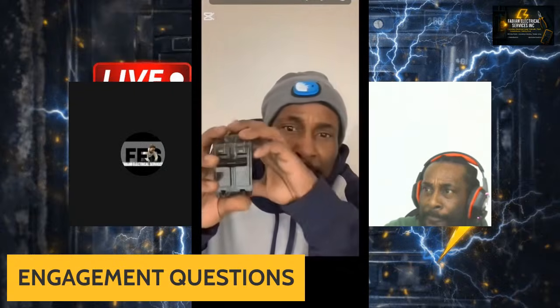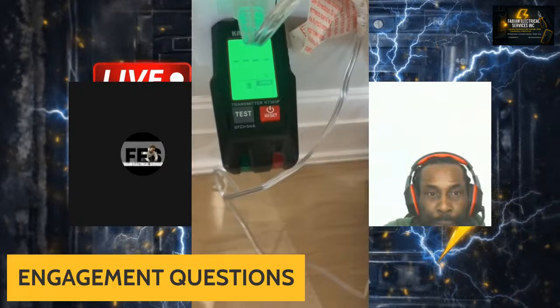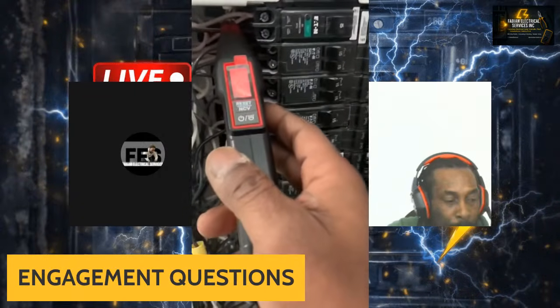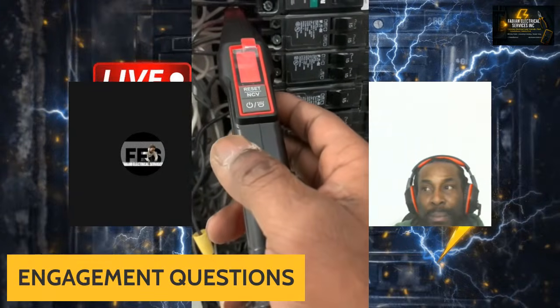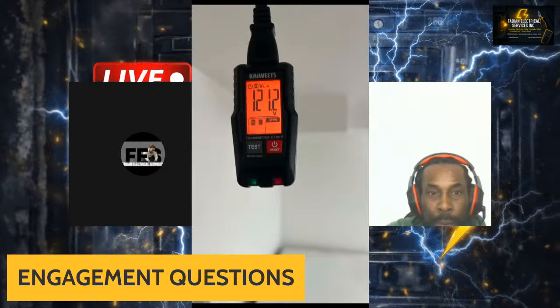Most electricians are using breakers wrong. A breaker protects the conductor, not the device. A 20 amp breaker can only carry 16 amps continuously. That's the 80% rule. Anything running over 3 hours is a continuous load. If you don't size this properly, you're setting yourself up for failure.